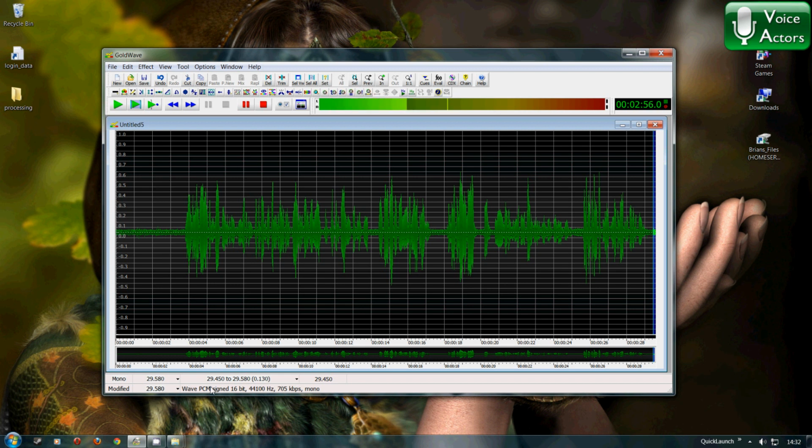But just remember, right, if your mic isn't capable of recording 16-bit 44.1 kHz, you're not going to get 16-bit 44.1 kHz even if it says you are getting it. It's going to record at a lower setting and just convert it to 16-bit 44.1 kHz automatically. And you're going to be able to tell because the audio won't be the same quality as that is. That should be CD quality, according to all the stats. It isn't really that, I don't think.